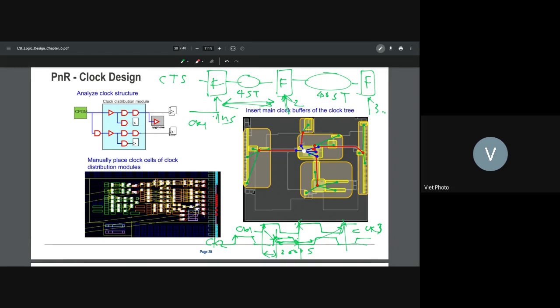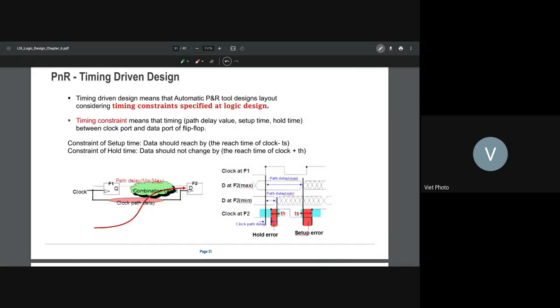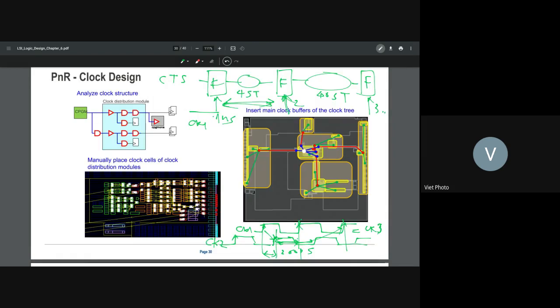It's not like in the placement, where it's all estimate, a kind of rough estimate based on the ideal clock. After the CTS they build the clock, right? Remember, I think I showed you that the clock will have to go to every input of the flop to provide the clock to be synced up with every other flop.